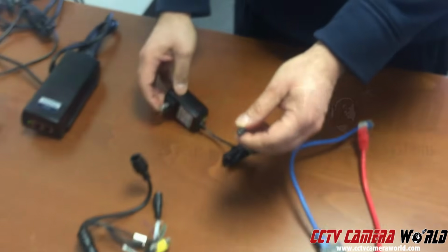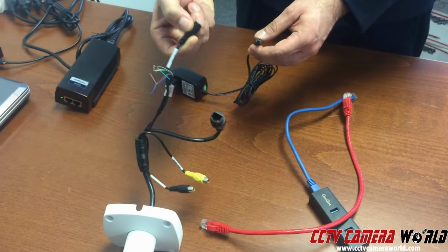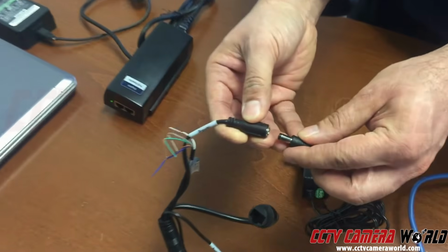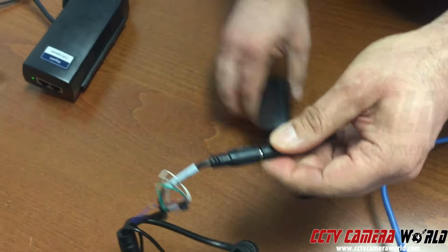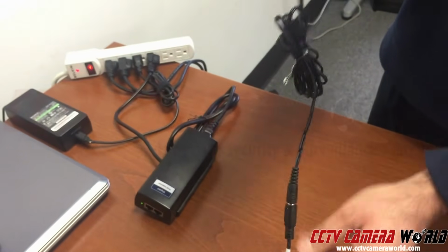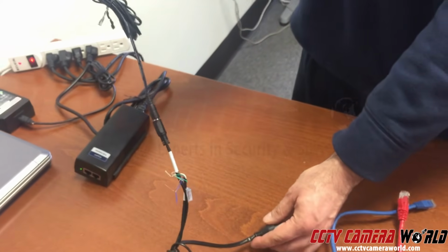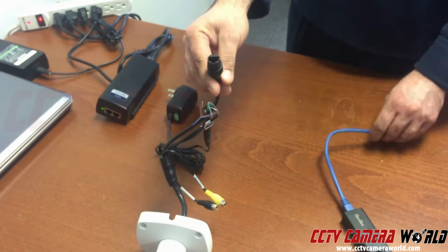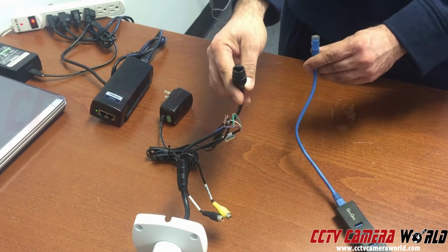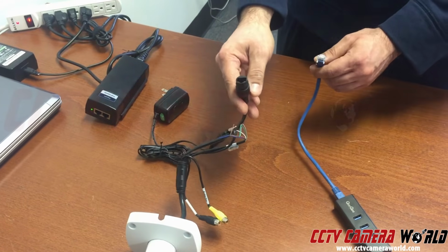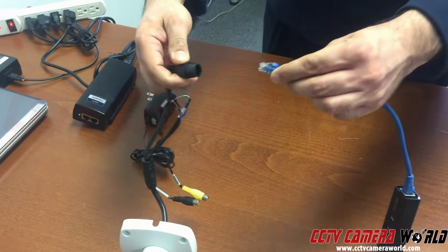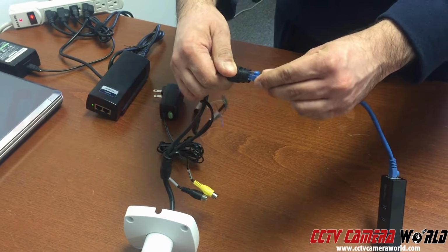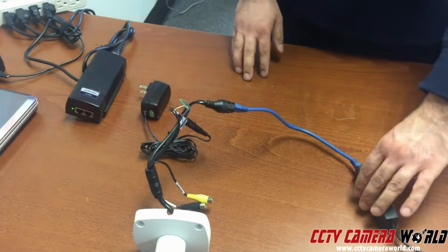So now I've got my power supply, and what I would do, to power the camera in this case, is use the DC jack on the back of it, on the pigtail, and connect it to my power supply, and connect the power supply to the wall. That would power the camera. Now to do this, you have to have the camera indoors, really right next to your laptop. Now a Cat5 connector on the back of a PoE camera is meant to function for both data and power, or data only. In this case, I'm going to connect it directly into my laptop. Hear the click, and you've got a data connection. Now watch here, it's not lighting up. That's because I haven't powered my camera yet.